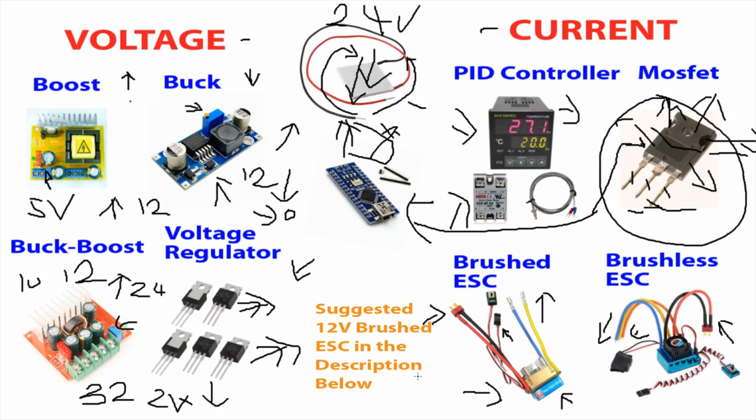Higher the frequency, theoretically you'll get a better efficiency, but how tangible the difference is, that's a debate. You could say that increasing the frequency of the MOSFET or the ESC will result in higher efficiency of the TEC but reduced efficiency of the speed controller itself, so total efficiency may be similar-ish. But anyway,